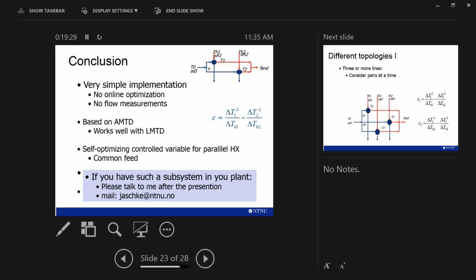To implement this online, can you get away with just a simple ratio control type scheme in order to just balance out your temperatures for long-term operation? What are you thinking? Well, a lot of what you were doing here was like a design methodology for how to balance it and compute where the appropriate point is. If you were to implement the scheme longer term, when you're going to have different fouling in different heat exchangers, so your temperatures are going to be changing over time, how would you implement a control scheme then, basically, to account for that? I would just make a... So you have a split. If you assume that you have one valve on one side that you can manipulate, then I just use a PI controller and control this to 0.